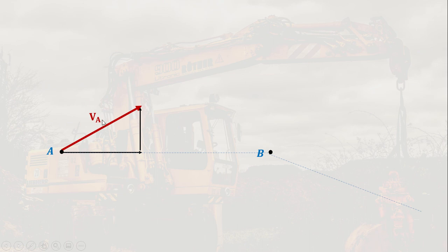So we basically get the components of A, the velocity of A. So these are the 2 components, along and perpendicular to the line joining A and B. And then we're going to measure this line, and then we're going to place that in the line at point B, because this component here is also the same velocity that is acting at point B in this line of action. So that's why we draw it here in the line connecting them, this component.